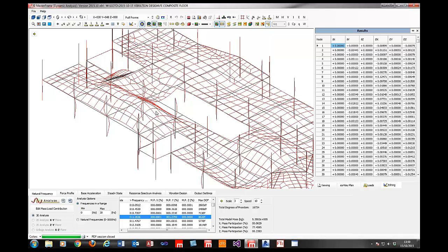But when it's the transient analysis, it doesn't actually reach that steady state, so we need to do something more sophisticated. And that sophistication is this transient analysis, which actually goes into more a full time history analysis, whereby it calculates the accelerations at lots of different time increments over a set period, and then it numerically sums up the root mean squared acceleration and then is able to transfer that into a response factor.